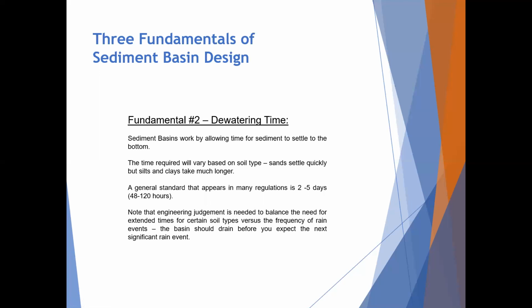So fundamental number 2 is dewatering time. Sediment basins work by allowing time for sediment to settle to the bottom. Obviously this time required will vary based on the soil type. If it's a sandy soil, it'll settle very quickly, typically within a few hours or even minutes. But silts and clays can take much longer and often are very difficult to get to settle. The most common standard that we see across the different states is 2 to 5 days, or 48 to 120 hours. But this does vary from state to state and even from MS4 to MS4 within states.